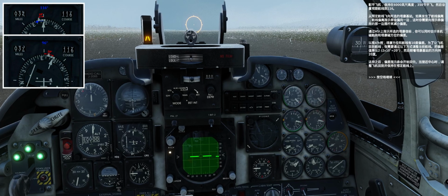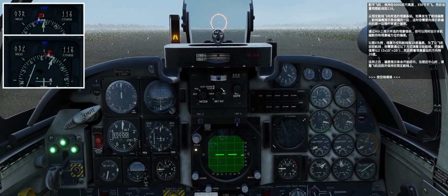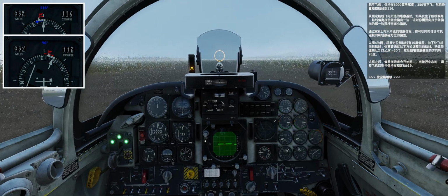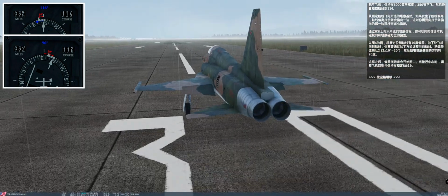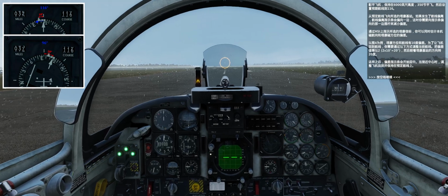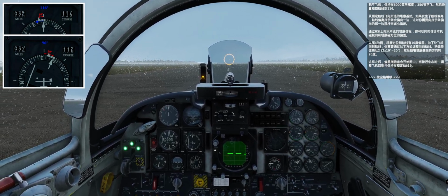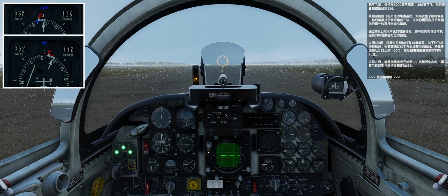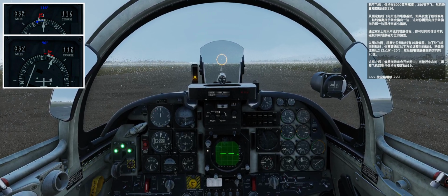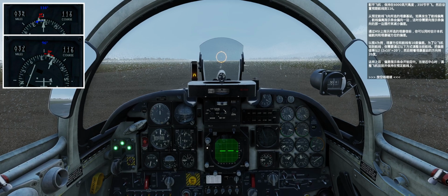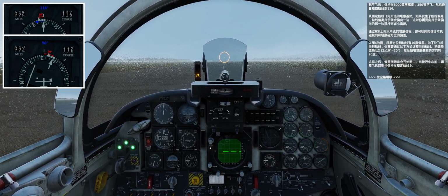Multiply the difference between the beacon bearing and current course by 2 and turn at 20 degrees towards the TACAN beacon. As a result, the course deviation bar begins to return to center position. When it is close to center, maintain the aircraft to the desired course. Press space to continue.